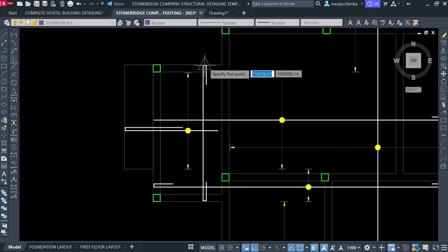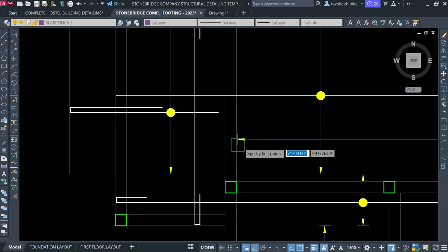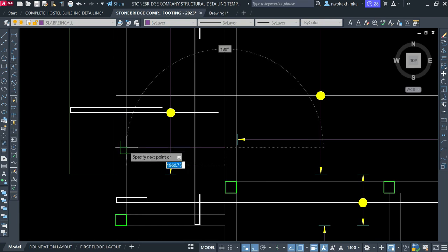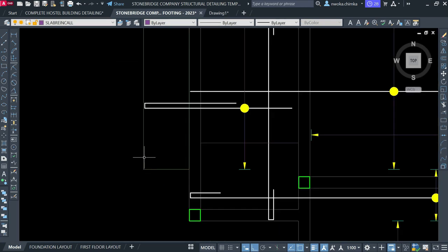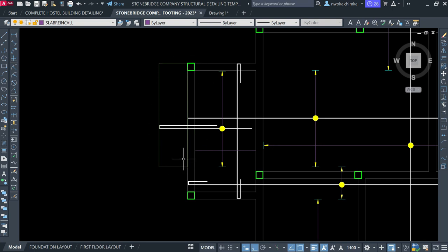And then this one right now picks up from the small panel here and then spans from where it stops. As it stops here, I'll start on this other end of the beam and then span to this place. Trying to cross here, it now finds a cantilever slab here, which is not full, just halfway. So this bar also has to stop directly at this place for the next bar to continue,